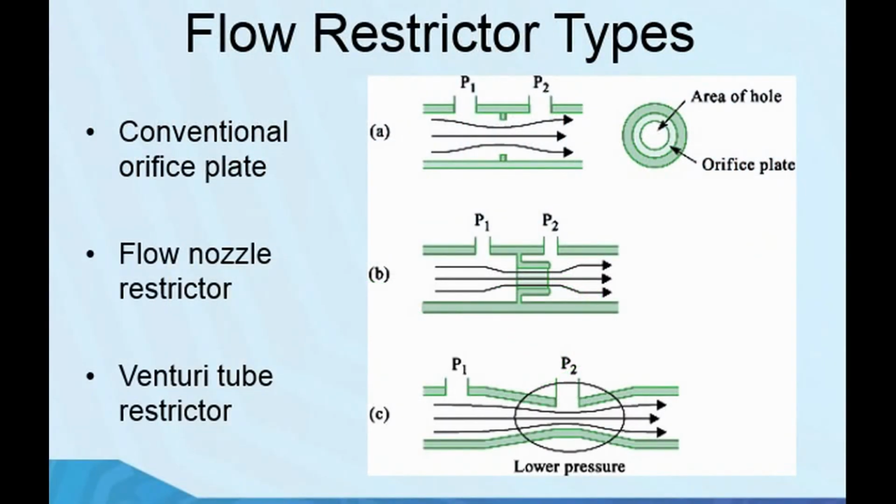Here are some methods for measuring the flow through a pipe, and these are based on Bernoulli's principle, which says that the pressure will change depending on the speed of the liquid. And these are inferred measurements because once again, you're not touching the fluid, but you are measuring something else. In this case, you're going to be measuring the change in pressure.